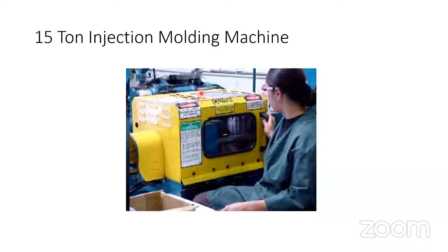Suppose I am giving you polyethylene. There are a number of grades of polyethylene: LDPE, LLDPE, MDPE, VLDPE, HDPE, ultra high molecular weight high density. There are five to six grades of polyethylene alone, and all the parameters change. There is no common parameter for this. Even within one family there are different types of polymers, with different monomers, as in engineering polymers.